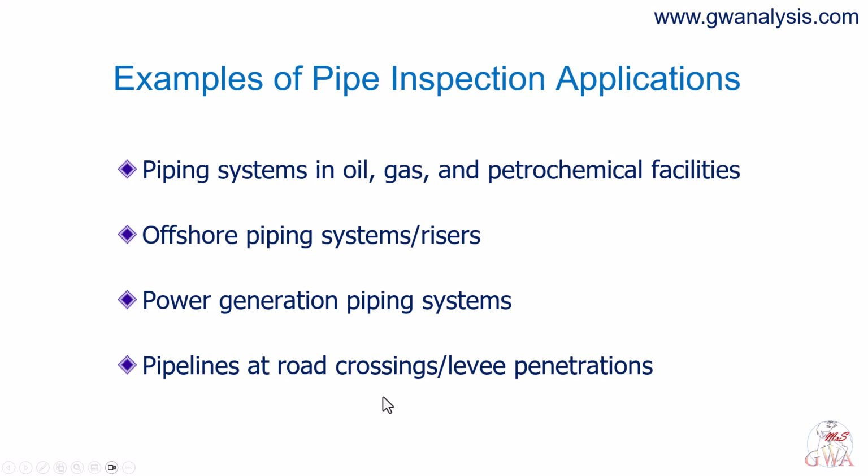Before we look at the photographs, one sentence about what we are actually doing, because it explains everything that follows. Guided wave testing is not a separate technology from ultrasonic testing. It is ultrasonic testing, where we use the fundamental torsional mode of the pipe, T(0,1). And that mode has exactly the same character as a shear wave in bulk material. The particle motion is circumferential, the velocity is the shear wave velocity of steel, and it does not disperse. That matters for 2 reasons that will come up again and again.